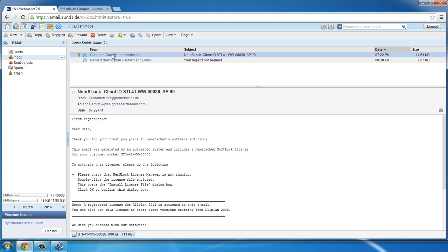It's important that you don't make any changes to the hardware from the time you request the license to the time you install it. Sometimes it's enough to just disconnect a wireless LAN stick and the license will fail to recognize the computer. You would then get the message that the license was not created for this computer or that it is defective. In this case, request a license again.